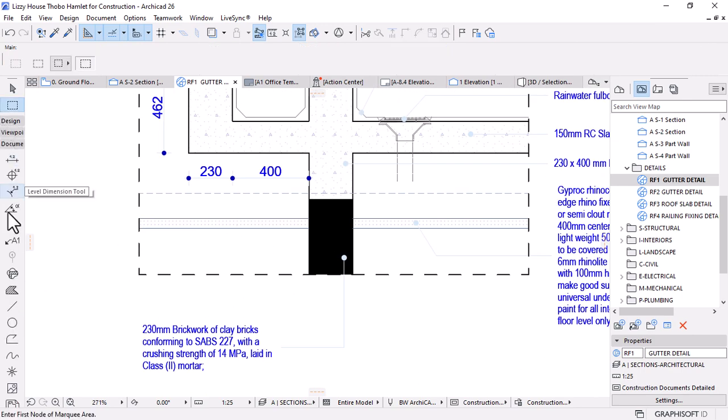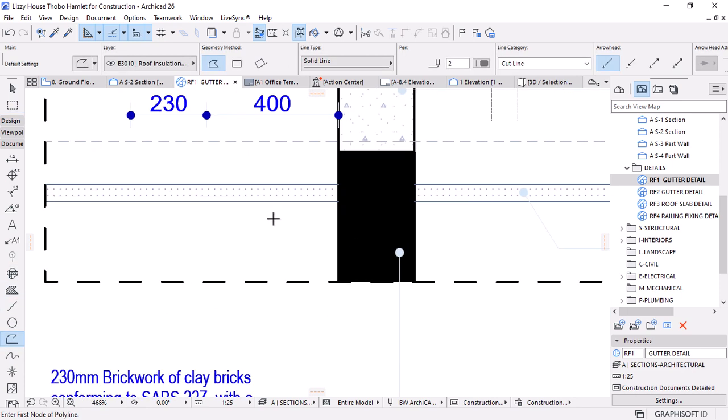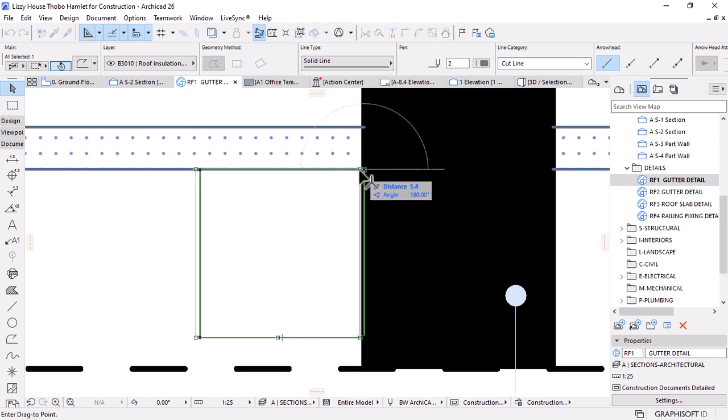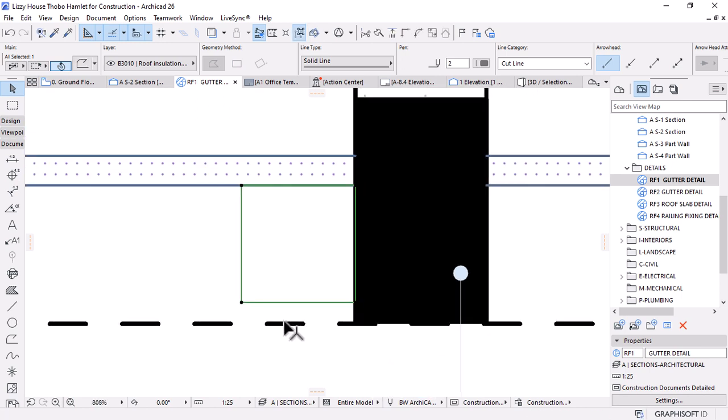we can do some sort of sketch there for ourselves. Let's use a polyline. Normally molds are like this, so I would say I'll draw a rectangle, a square of 150 or 200 by 200, something like this, and then let me move it to the point extrude. Alright, so what I'll do is insert a point, or before I insert a point, I'll draw a distance of 40, 50.